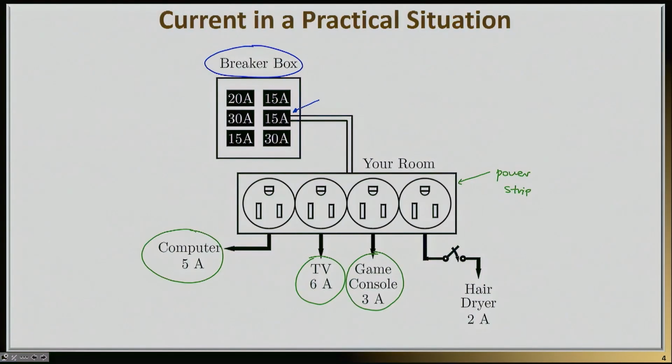There could be several scenarios where you might draw too much current. For example, you may have an accident or a short circuit. If some bad connection attempts to draw more current than the circuit breaker indicates, in this case 15 amps, then the circuit breaker will trip and create an open circuit, stopping the flow of current.